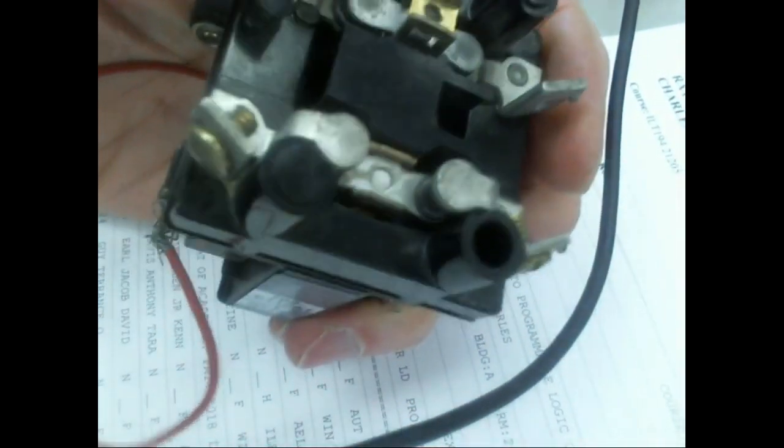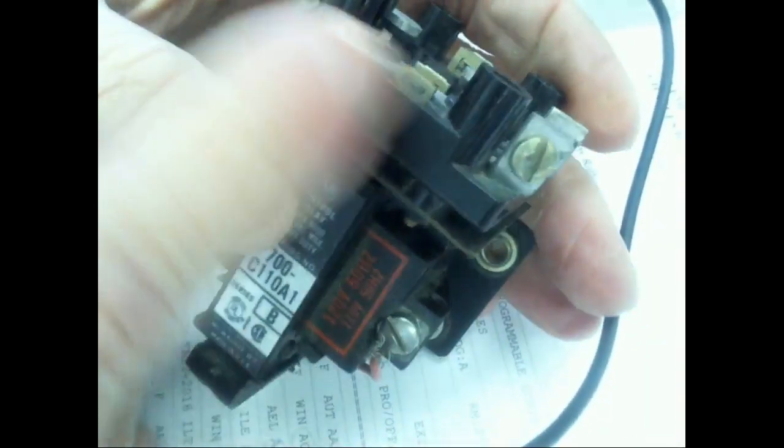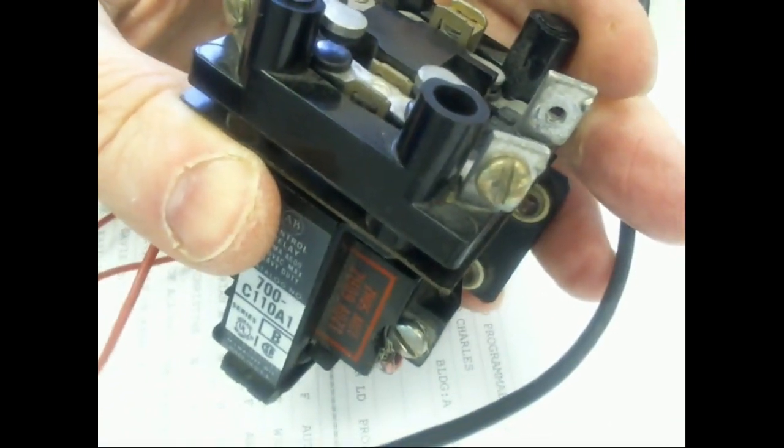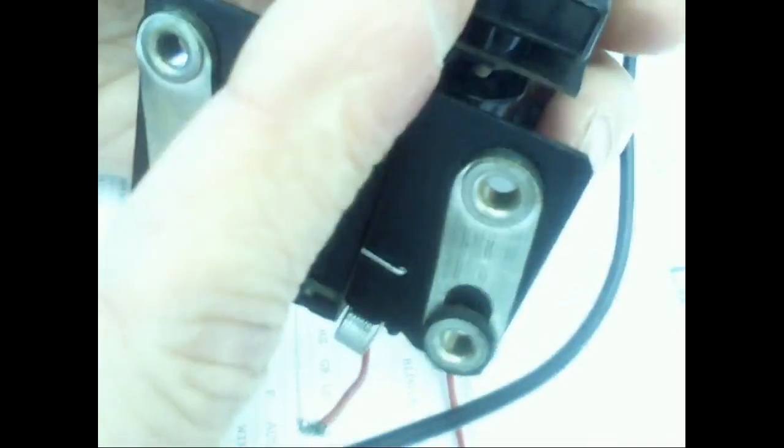So we call these contacts. We don't call them switches. We call them contacts. And we have what we call normally open contacts. So if my solenoid is not energized, these contacts would be open, so the light switch would be off, right? You understand? Over here, these contacts are closed, so those lights would be on. So when I energize this solenoid, these contacts change states. This is what we call a relay, and it's an electrically controlled switch.